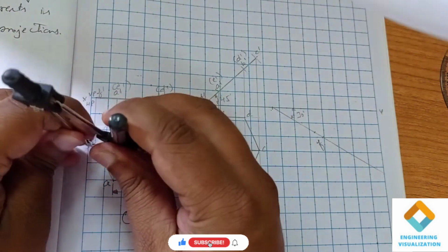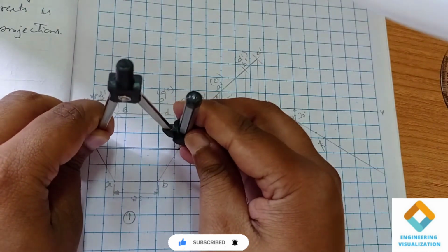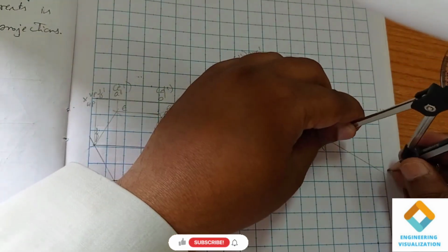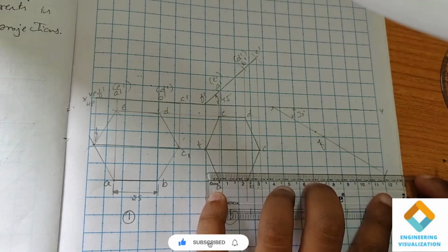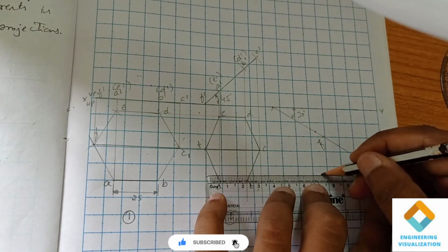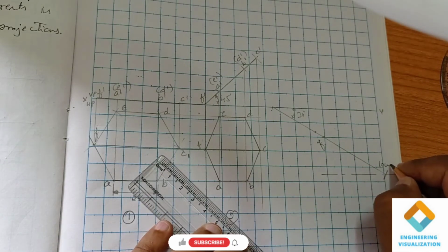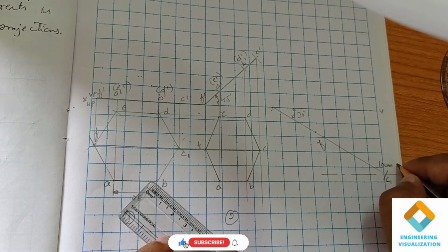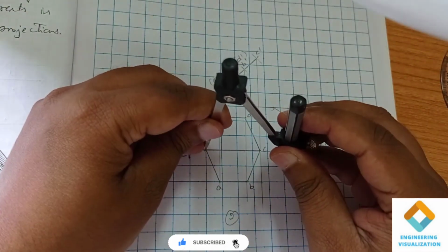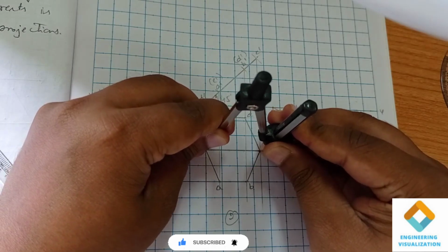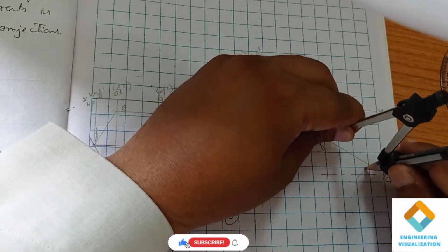Okay, now with the beta angle concept, first this length FC1 we have to consider. We are cutting the arc. Okay, so after cutting the arc, exactly to this point we have to draw a locus. So this is C1, locus of C. After this the second arc length we have to cut, that is this one, FC. We have to measure FC and cut it on this locus line.